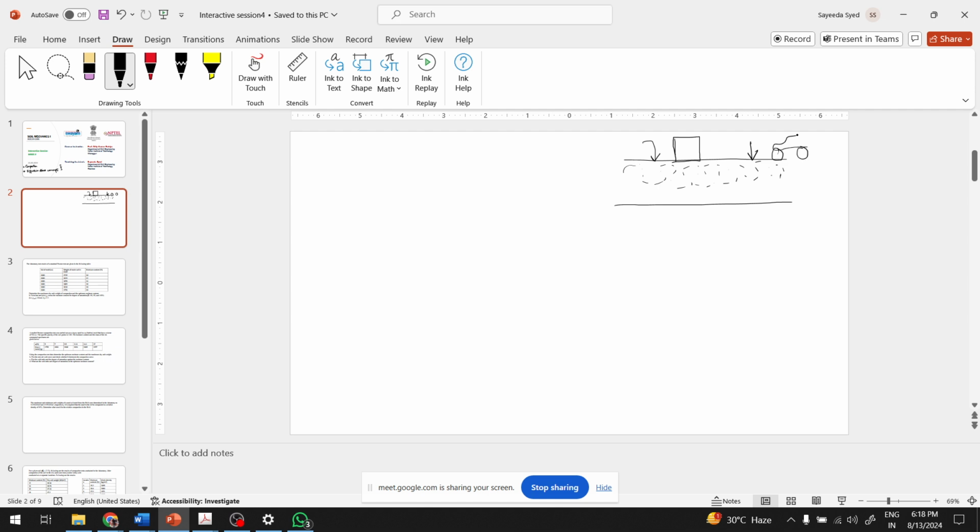We make multiple passes of these rollers over the soil so that the air voids reduce. It's very important to know that compaction of soil takes place due to escape of air from the voids and not water. When water is escaping from the voids, it is most likely due to a consolidation process.